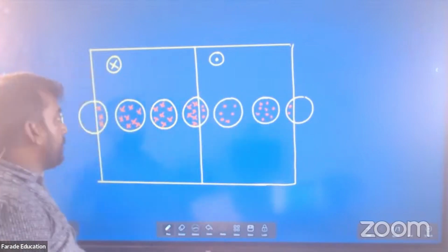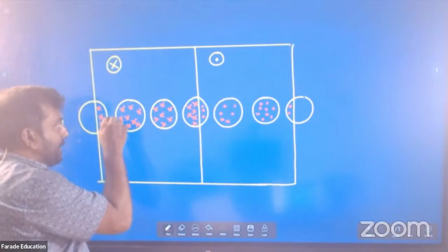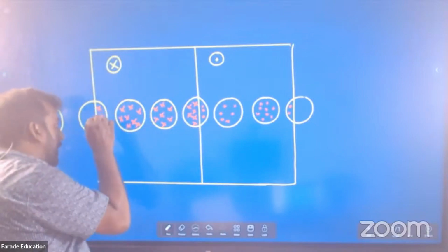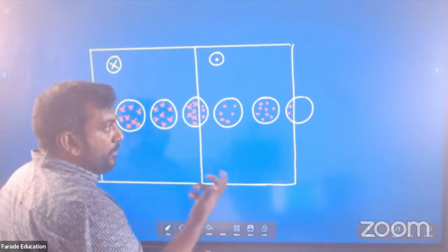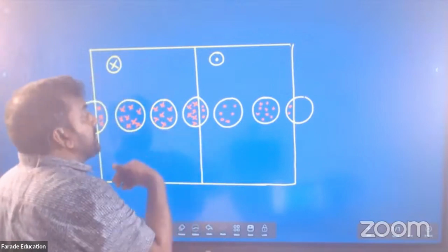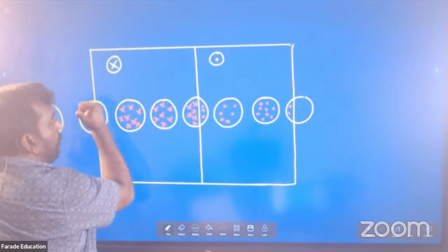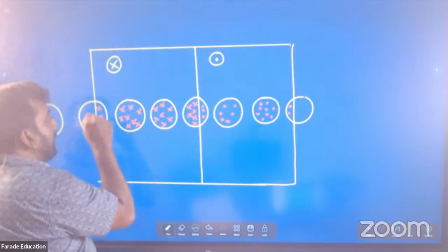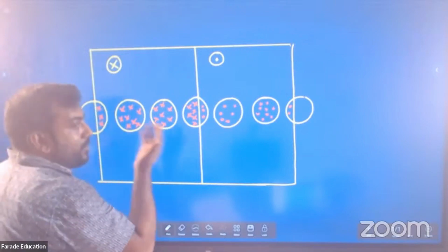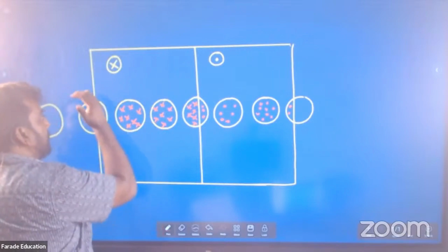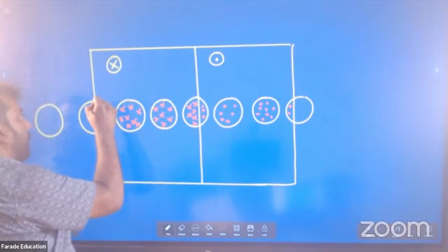Fleming's right hand rule, or you use the right hand rule. Little by little, the number of field lines entering increases. According to the law of electromagnetic induction, it must oppose the change. Field lines are increasing inwards, we must oppose it, so keep the thumb outward. Field lines are going inwards, we must cancel it. So field lines should come outward. Cancelling the field lines means current will go like this.